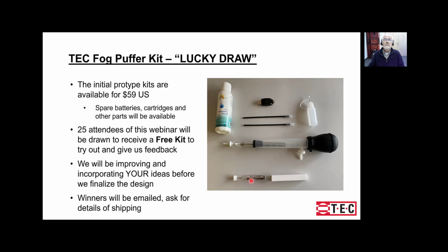And then you'll also get a spare cartridge, so that if that fails. Out of all of the testing that I've done, I've had about 4 batteries fail, and I think it's always been the pressure switch, although I have not taken them all apart to verify that. And I've had no cartridges with the heaters fail, which surprised me. I thought that would be the main failure.